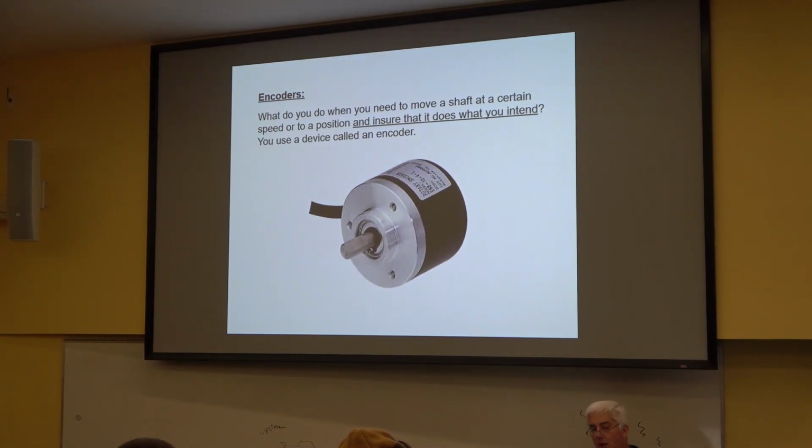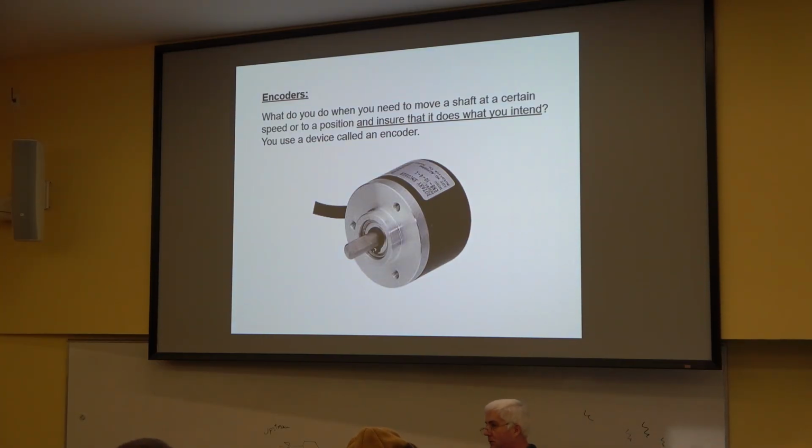So when you have a control system, a lot of times you're going to send a command to a motor, a power stage, something like that, and you've got to say, did it actually happen? Okay, feedback. That's what your encoder is all about. So for example, if I say I want a stepper motor to move one click, I can use an encoder to check that I actually got one click of revolution on my stepper motor. And if I don't get that within a certain time, I can throw up an error signal and say, hey, warning, something's jammed. Operator, intervene.